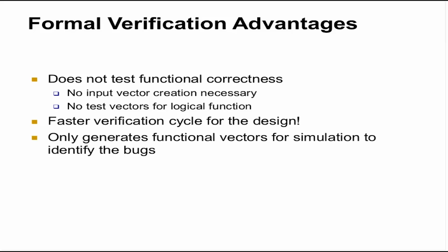But once you are satisfied that your RTL is correct, all other versions of this RTL can be verified against the reference. What could those versions be? That could be a synthesized netlist, or a post layout netlist, and the process of verification is comparatively faster.